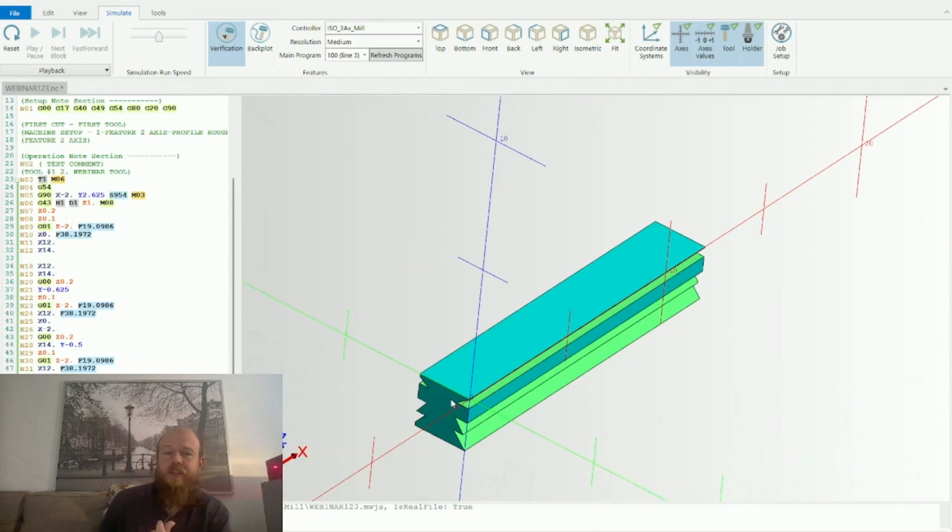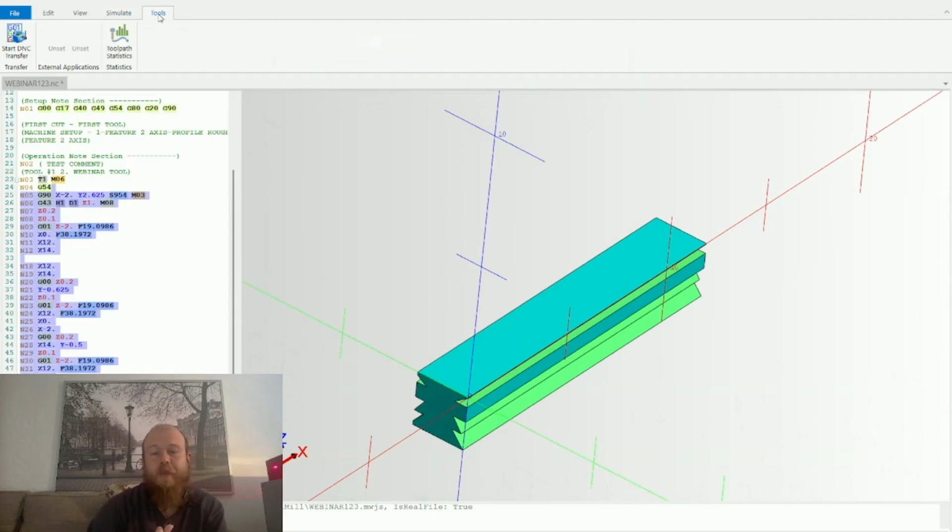It only simulates the graphics of the toolpath. So if you have anything incorrect in the G-code here, the NC Editor will actually show you if there's any incorrect G-code being output. If there's a gouge move in the actual G-code, it'll read it and show you here. It'll actually give you an error if there's anything, a plunge move into your vise that you can bring in, things like that. Then our last tab here is Tools.